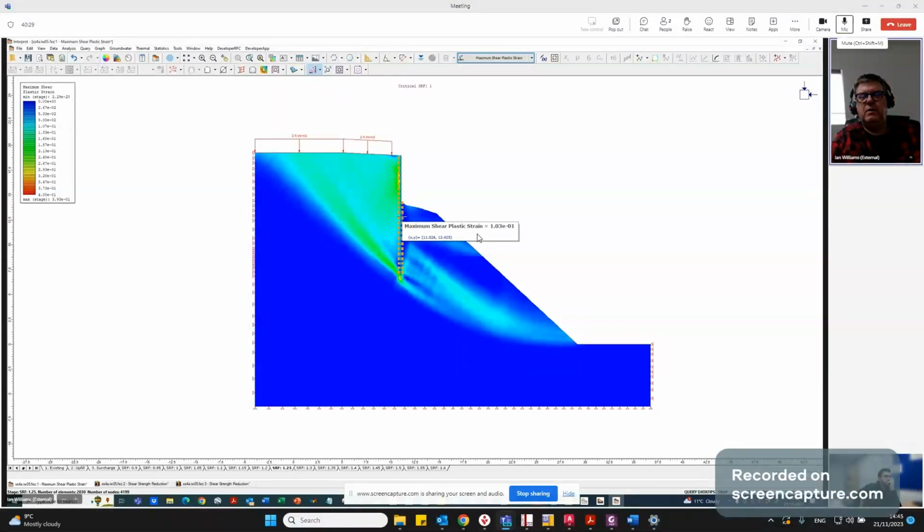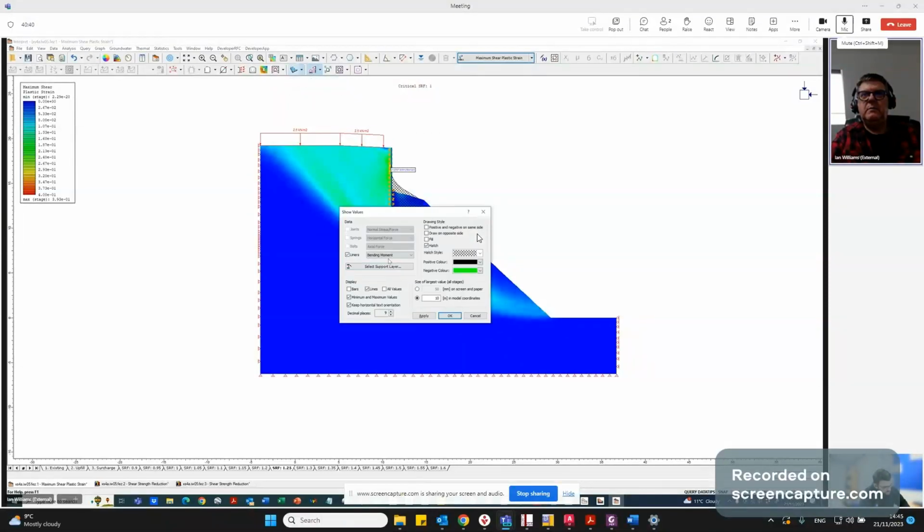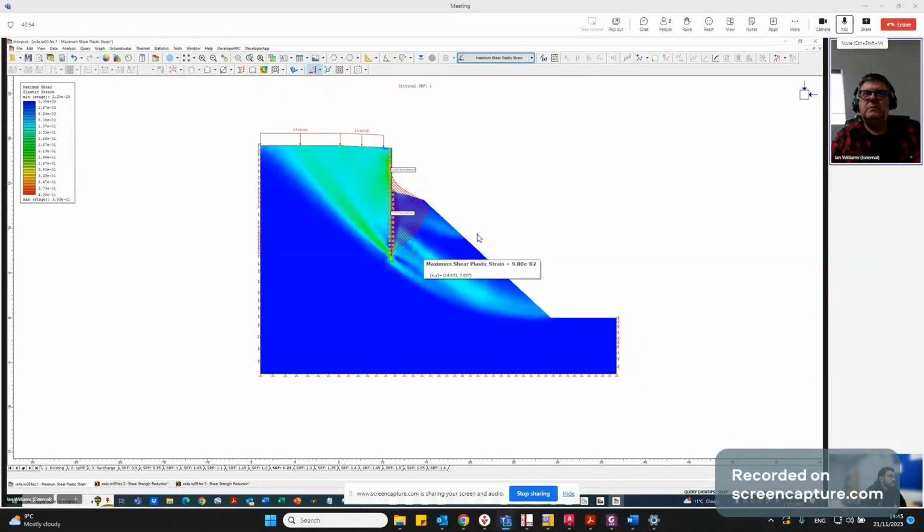The wall, by the way, I've modeled as elastic. So one of the checks you would have to do is, do these bending moments... can they be carried by the wall? Can the wall actually support those moments? That would be designing my wall basically to those moments. Yeah, that would be a simple check for you to do.